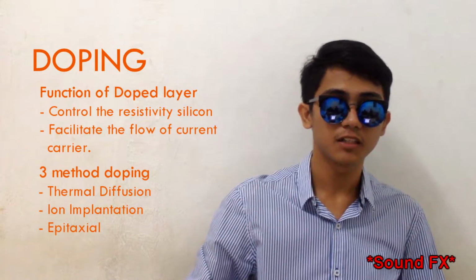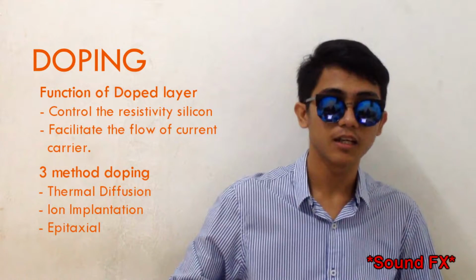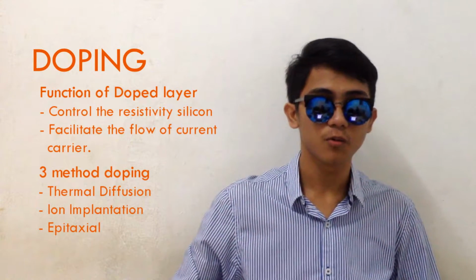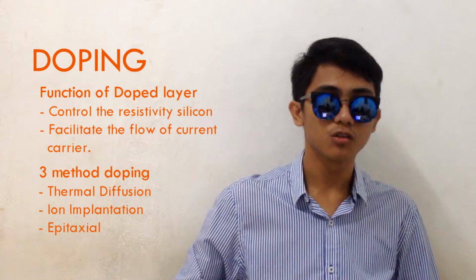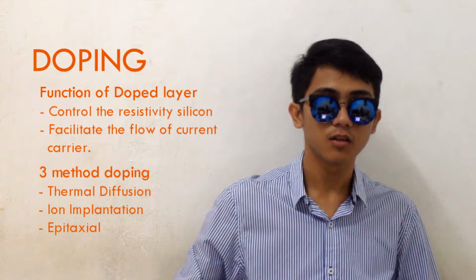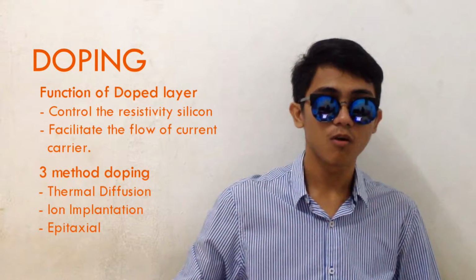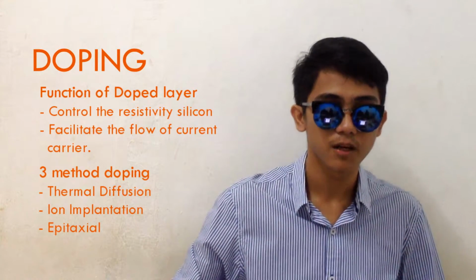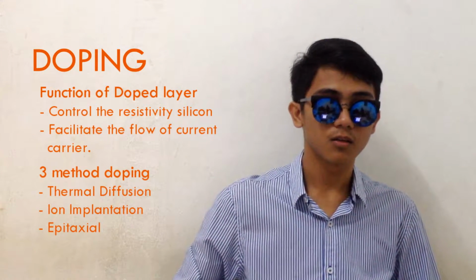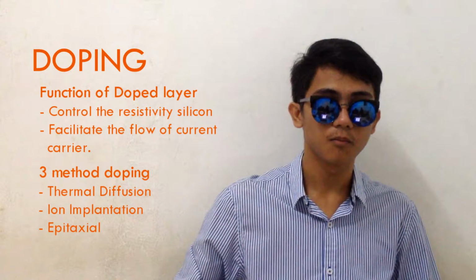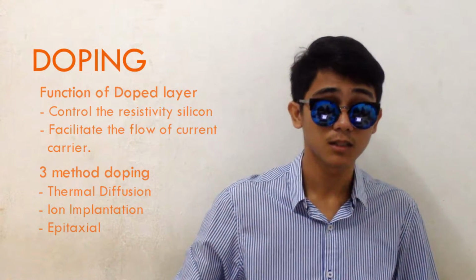Advantage and disadvantage of ion implantation. The accuracy of dopant position and density can be controlled with high precision. The thickness of the dopant is uniform. It uses low temperature, at room temperature. Atoms are doped directly into the wafer surface, reducing the crystal damage caused by high temperature. The disadvantage is that it causes defects to the crystal lattice by the dopant atoms. High cost of equipment, and production of wafers is limited.